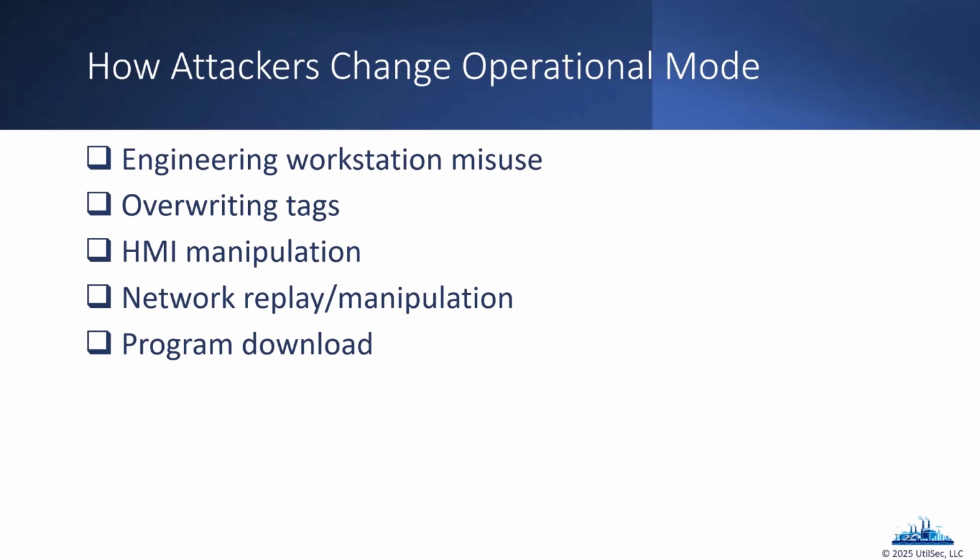And we can also capture network traffic, right? We can capture commands like from the HMI to the PLC, and then we can replay those later at a time of our own choosing. Or maybe we can even make changes to the data before we resend it. So that's one option. And we'll start to see that kind of an attacker in the middle attack, or now what they call in-path attacks. I still like attacker in the middle better.